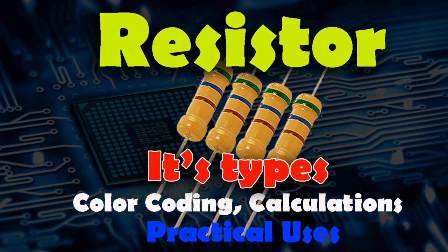A voltage divider network is used to provide a stable base voltage. This is one of the most common and reliable methods for biasing BJTs. Advantages: provides excellent stability of the operating point, relatively insensitive to variations in beta. Disadvantages: requires more components, resistors, than other methods.